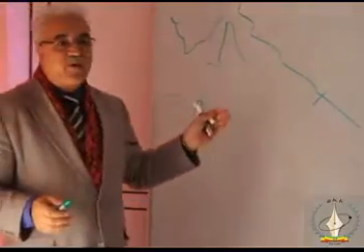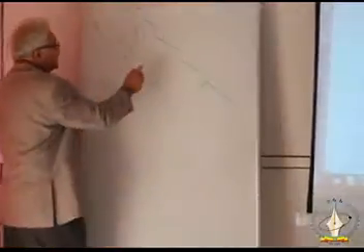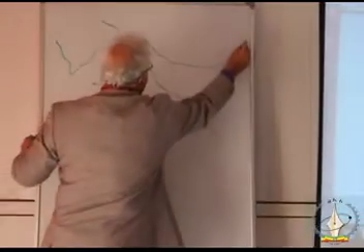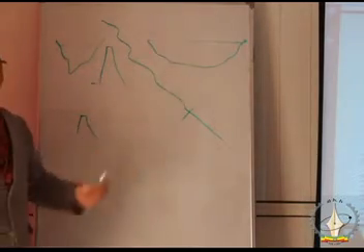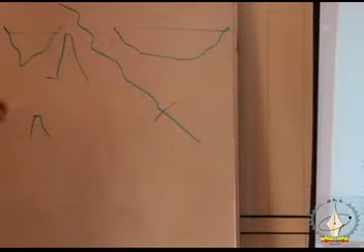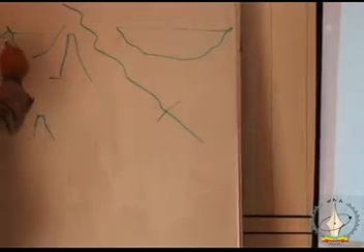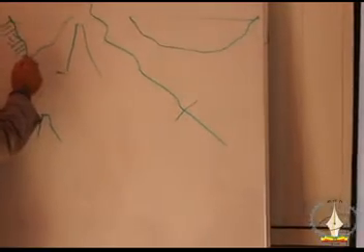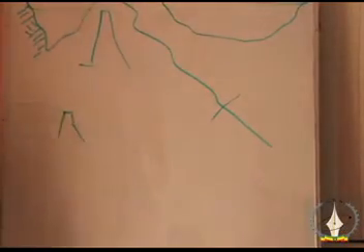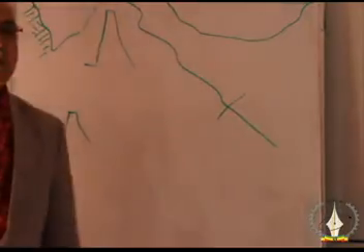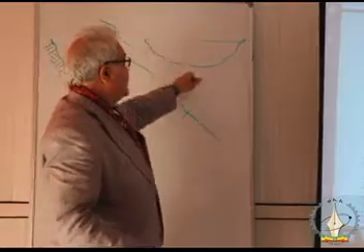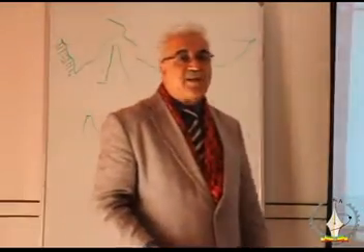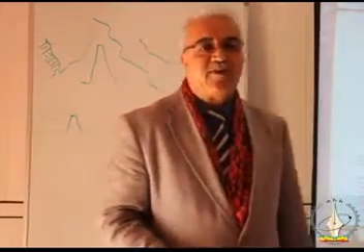And also from this information, if the valley is something like this, then you see there will be a big, very lengthy dam for the same amount of water to be stored. If we are talking about very mountainous areas with rocky cross sections, that may be good for a concrete dam. But if you find something that is not really rocky, don't try to build a concrete dam.